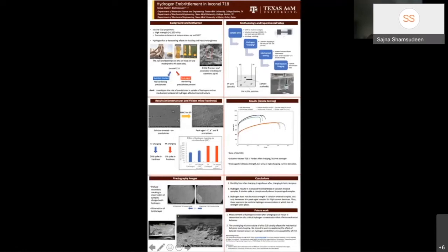An oil hose is shown here, the fasteners on which are made from a family of nickel alloys. These fasteners failed catastrophically and suddenly, and subsequent SEM analysis showed that they exhibited brittle fracture and secondary cracking, both of which are hallmarks of hydrogen embrittlement.